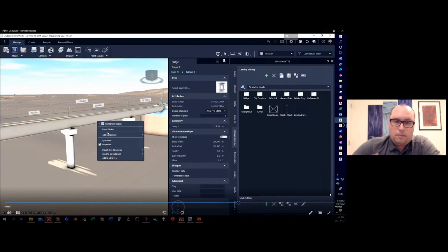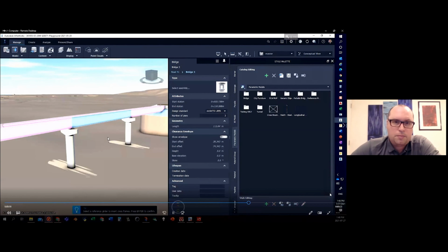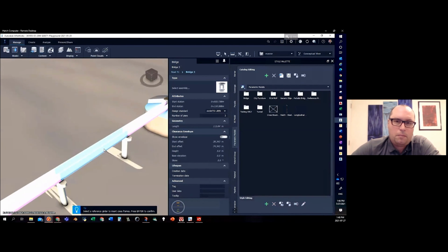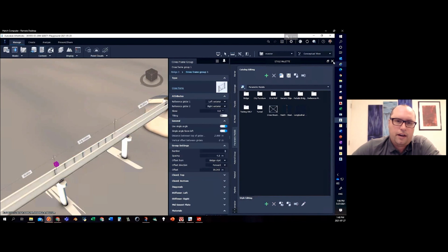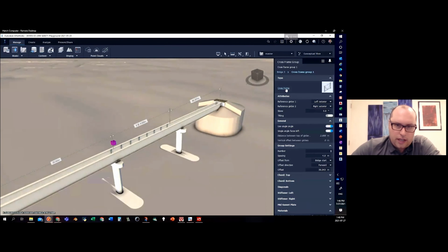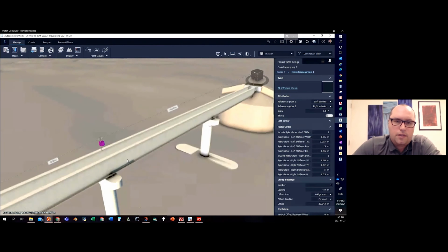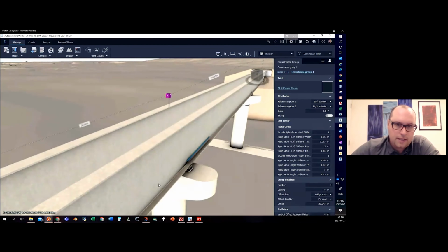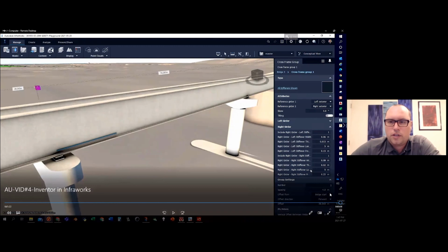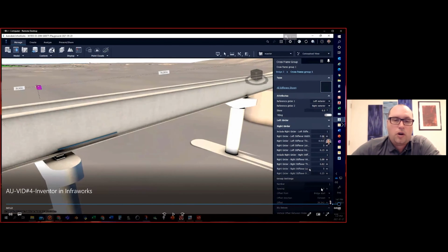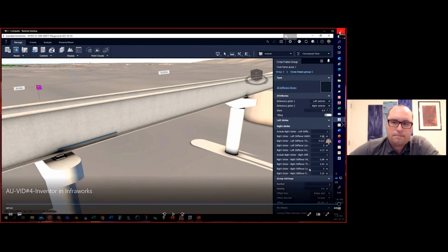And then I've got it. To put them in, there's lots of tutorials about it, but you essentially click cross frame. It will stupidly put in as many cross frames as it can fit into that area. And then you have to go in and change the number down to 1 if you want 1. And then wait, and then you change it back to the specific size of the stiffeners that you want. So then it's in there. And then you can change any of the parameters that you've described and tagged to there. And then the model will start to adapt to it. And as well, if I change the beams, then everything will adapt from that. So that's it.